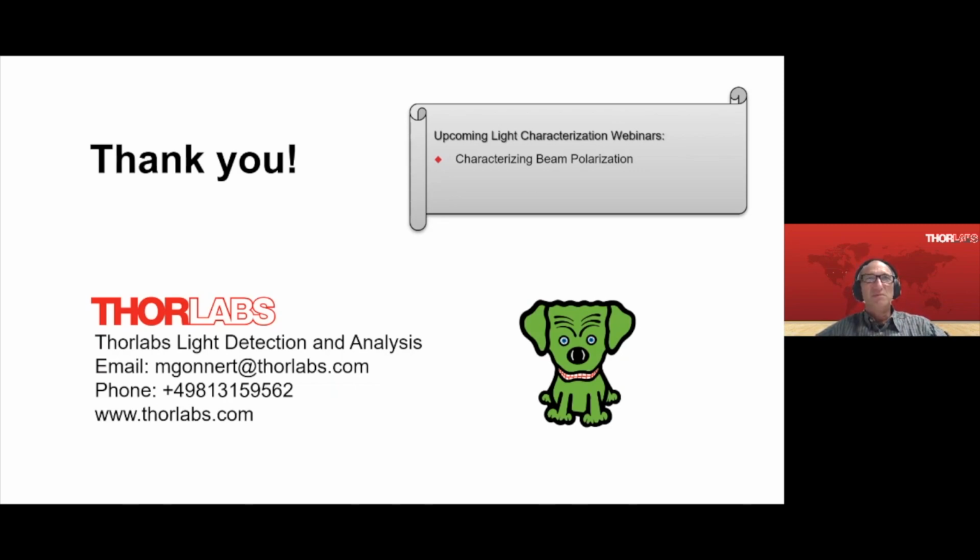Okay, there are a lot of very different questions, so I'll get to another one. On the comparison page with the camera beam profiler and the scanning slit beam profiler, it was written that the camera uses the 4 sigma method and the scanning slit the 1 over e squared. The customer would like to know if the camera could be set up in the software to also use the 1 over e squared method. Yes, this is possible. Okay, great.